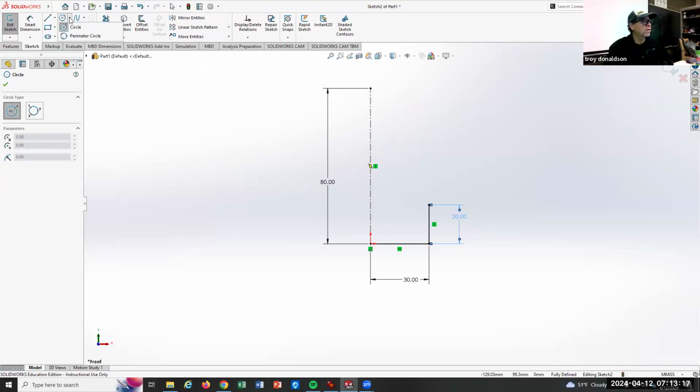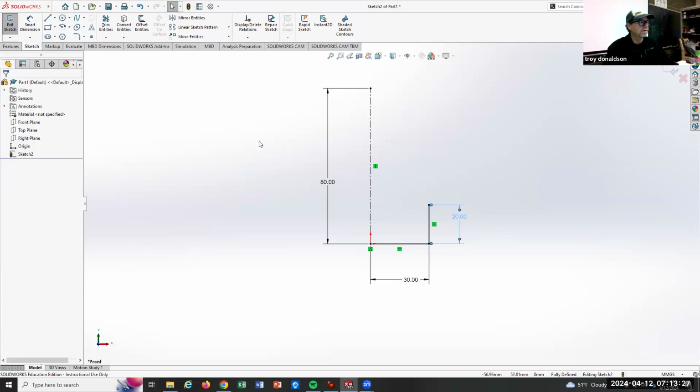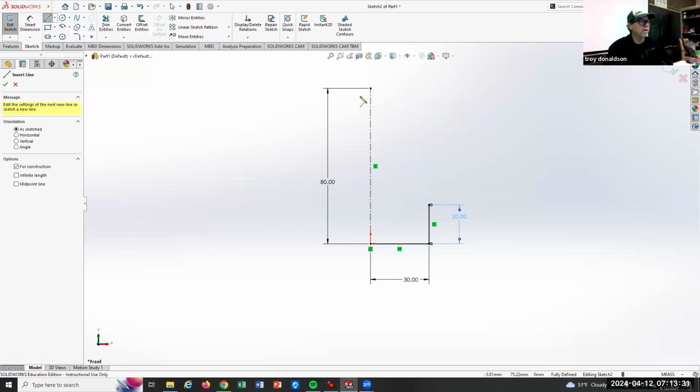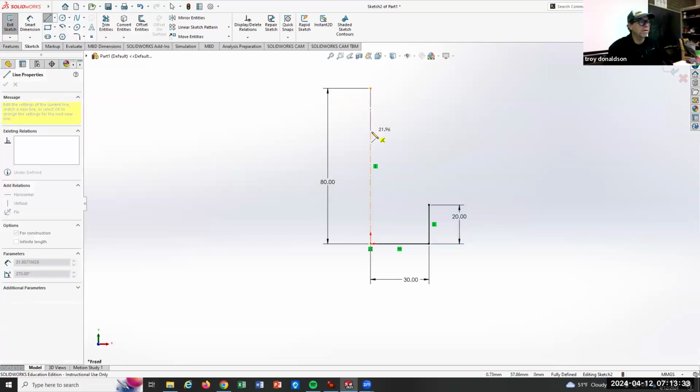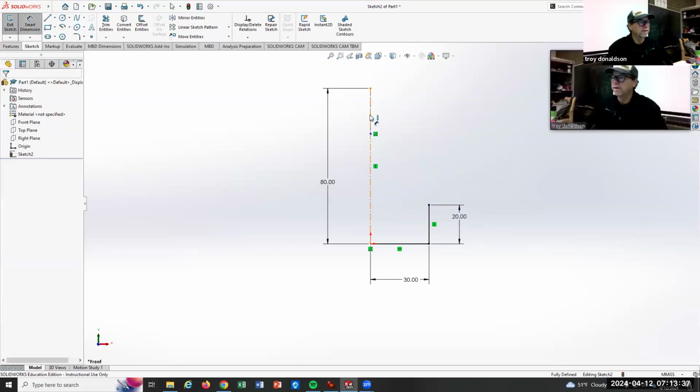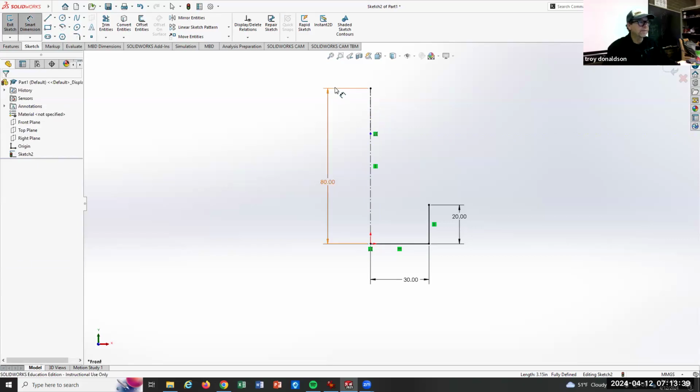If you look at this, there's a couple different ways to draw a circle. I don't like either one of them. This is a radius, but I don't know where that center point is, right? So I could do a couple things here. I could do another center line that comes down, and then I could dimension it. So that's one way to do it.